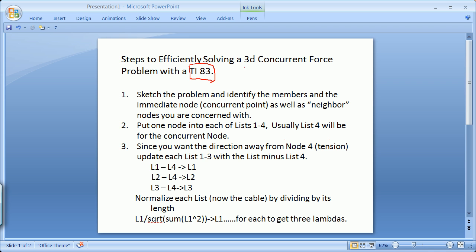If you remember, up to now we've basically talked about that what you need to do is make a matrix where you had the direction of one vector here, the direction of the other vector, and the opposite of the knowns there. This is a 2D problem, or for a 3D problem the same thing stacked up: 1, 2, 3, the directions of the unknowns, and then finally here the magnitude of the opposite of the knowns, and use the RREF function.